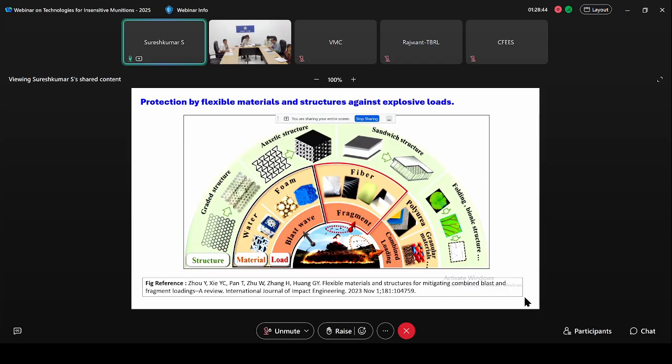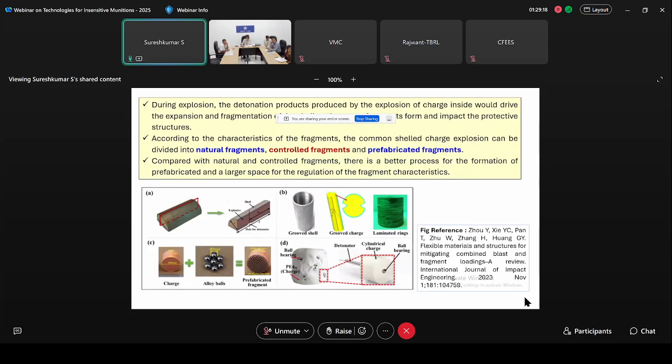An experimental focus is not yet planned right now. Numerically it can be achieved by using the numerical code Abaqus 2025 version along with the composite modeler. Whenever an explosion happens, first the shock wave generates, followed by the fragmentation. If it is in close proximity, the fragmentation attacks the target before the shock wave reaches it. Similarly, as the distance increases, the reverse case also happens. So how to model it using numerical simulation is our main objective.